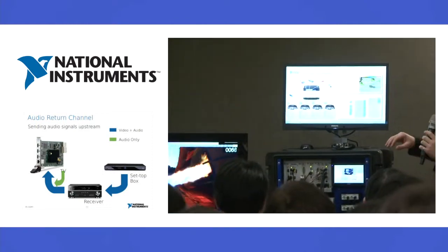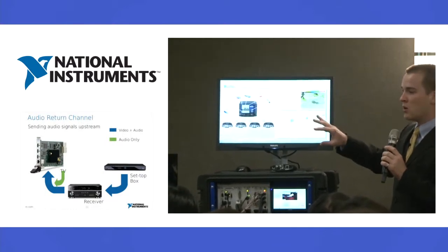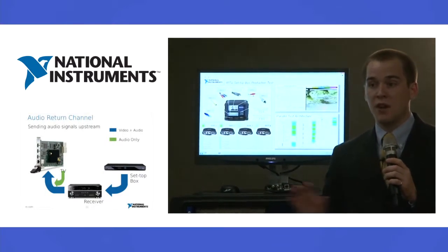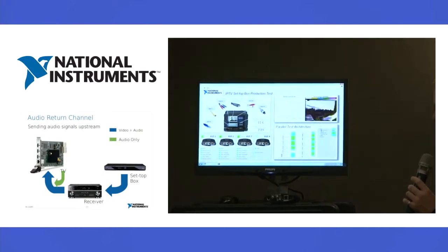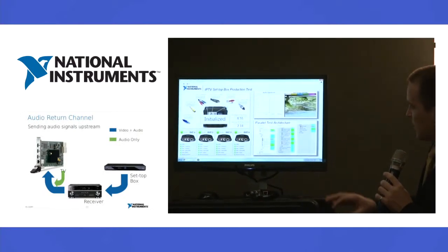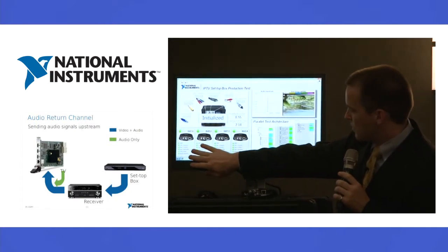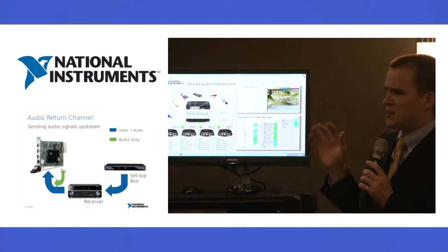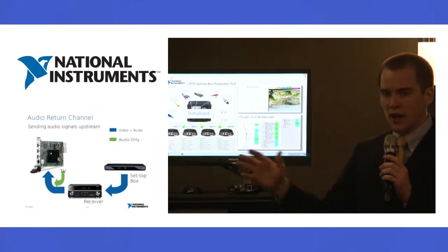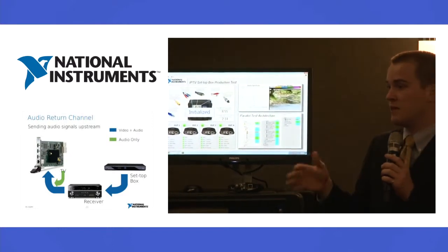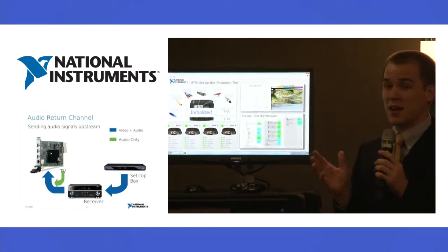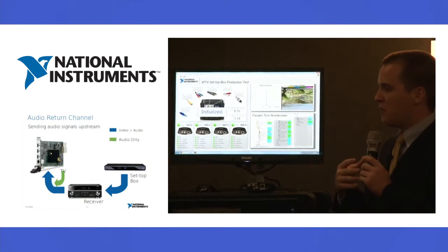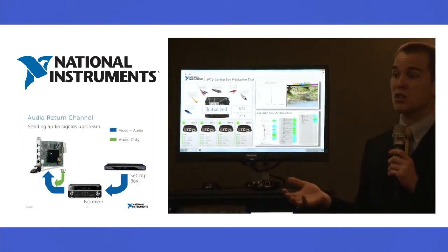It'll run through the sequence one time, but we're basically testing all of these different interfaces on all 4 set-top boxes very, very rapidly. So it's going to fire through and test each of those components for each of the DUTs very, very rapidly. And it does about 400 measurements total, compares those to the limits, and gives everything a pass-fail in about 8 seconds. So it's very high performance, high throughput. It's very useful for production applications.